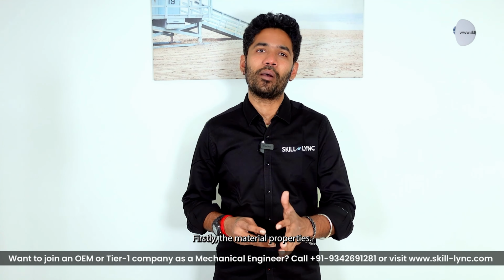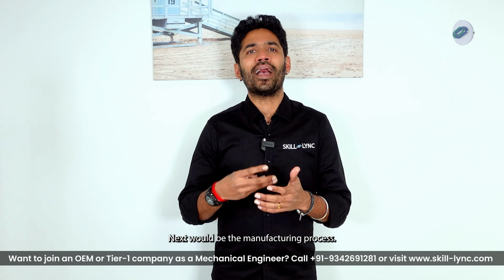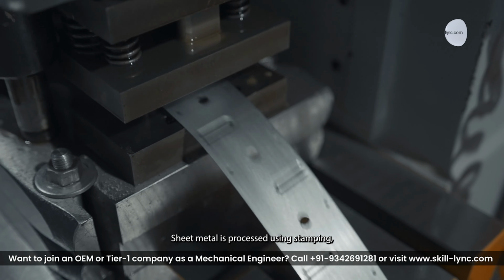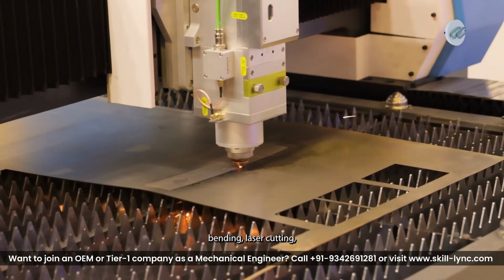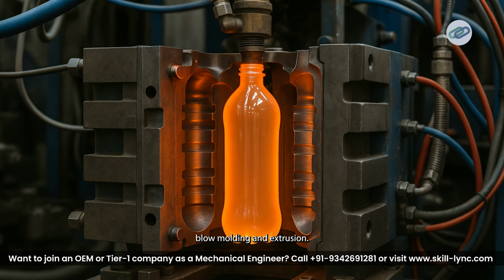Firstly, the material properties. Sheet metal is stronger while plastic is lighter and flexible. Next would be the manufacturing process. Sheet metal is processed using stamping, bending, laser cutting, while plastic is shaped through injection molding, blow molding and extrusion.